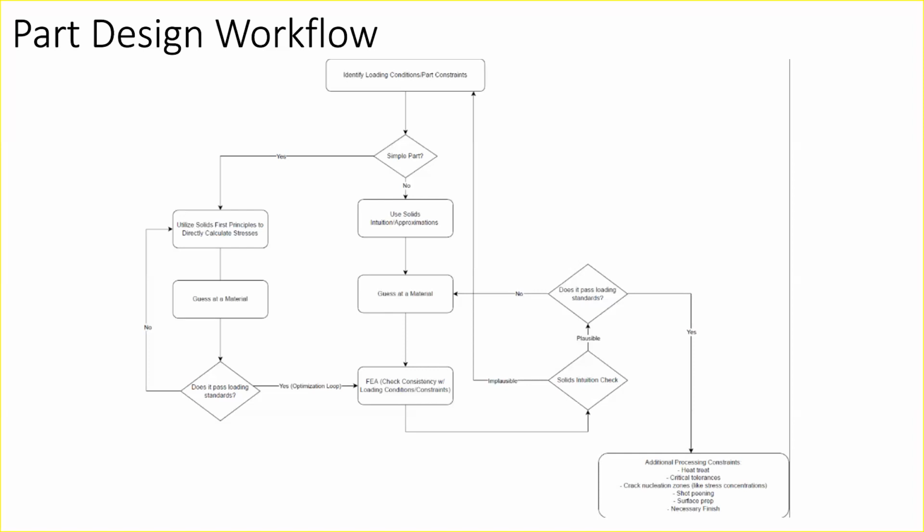So there are fundamental differences in the behavior of these two parts, but carbon fiber is much more difficult to analyze specifically because of the anisotropy. It behaves differently in different directions, and the material properties are also difficult to predict. So there's a much higher bar for analysis for those kinds of parts, which is typically why we don't encourage new members to start with those. Start with the predictable parts, and once you understand that and can characterize them, work your way up to the more advanced stuff. So yeah.